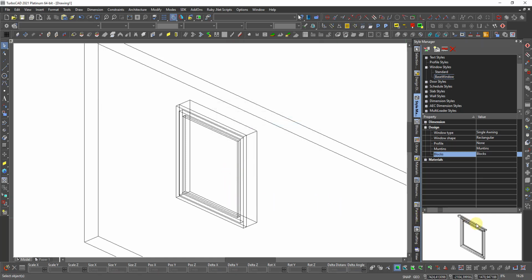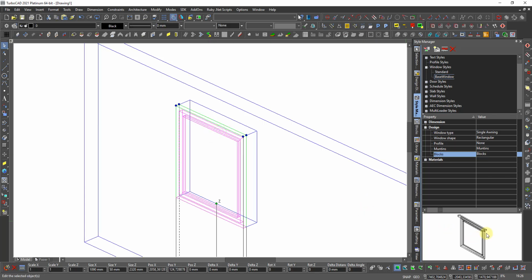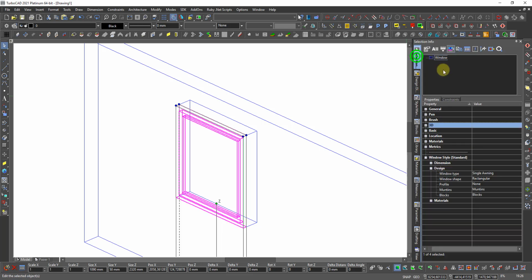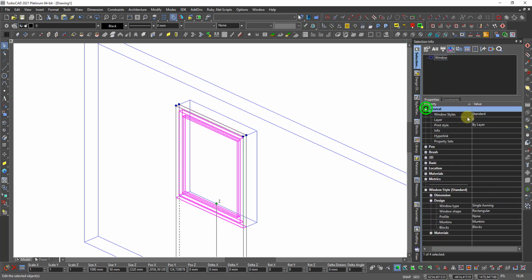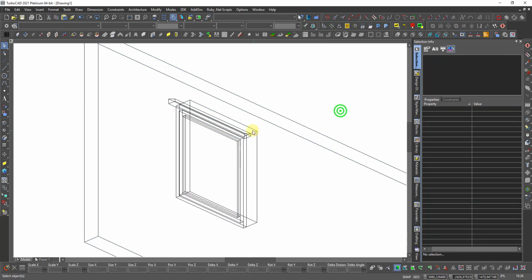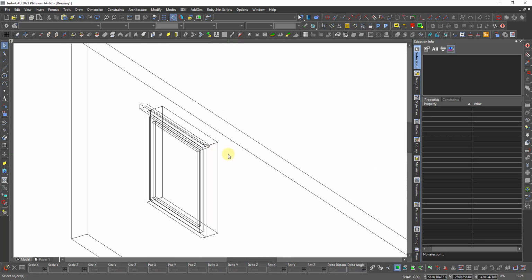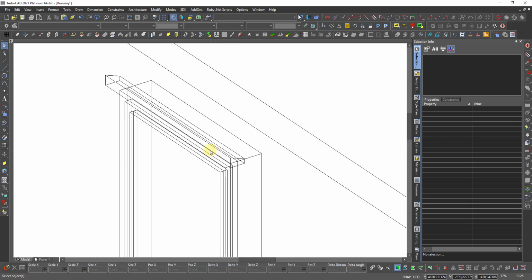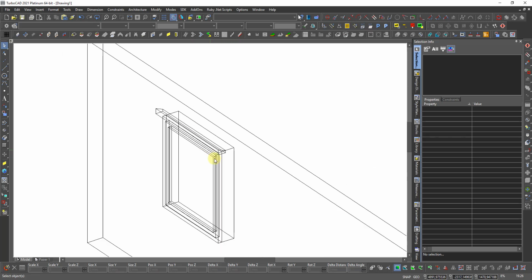It's shown here, but not there because I have not changed that window. But it looks like it goes the wrong way. So I go here and say this window is not standard, it should be base window. And there it shows that everything comes the wrong way. I should have rotated the window before I made the block. Now I need to go and fix the block.